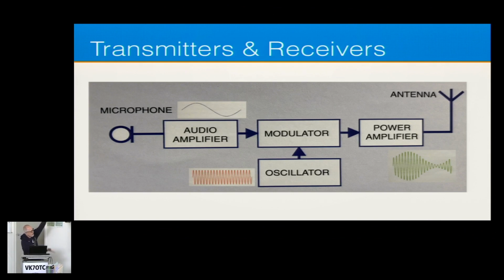Now, if you're looking at a power meter, an external power meter with a little meter on it, or some of them are built into the transmitter, and you say hello, hello, or your call sign, so you've got a bit of voice modulation there, and the power meter tells you it sort of averages around about 10 watts, you're spot on. You're only putting out 10 watts of power, so you're within your license conditions.